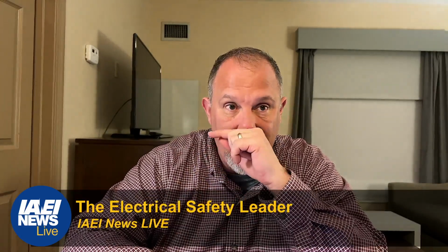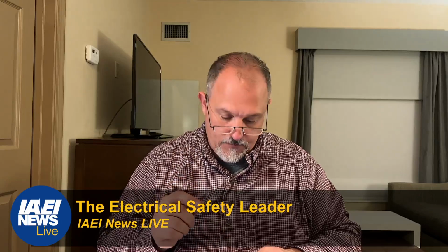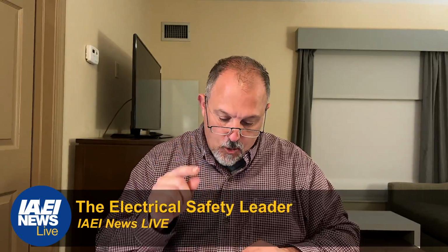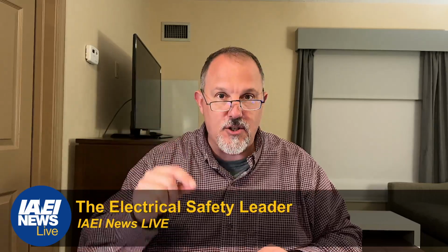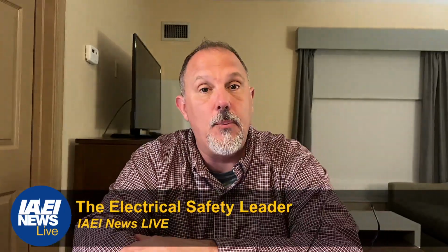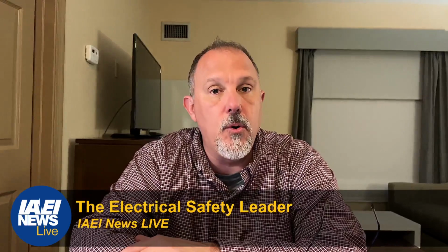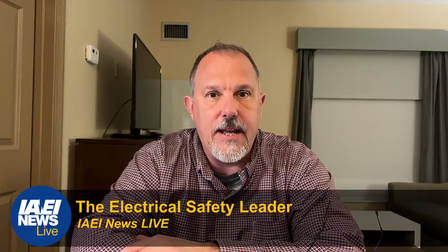So what we did in 210.8(B) is we said sinks where receptacles, or this is the adder, cord and plug connected fixed or stationary appliances are installed within 6 feet from the top inside edge of the bowl of the sink. So what we did there was we pulled in the fact that it's the appliance.